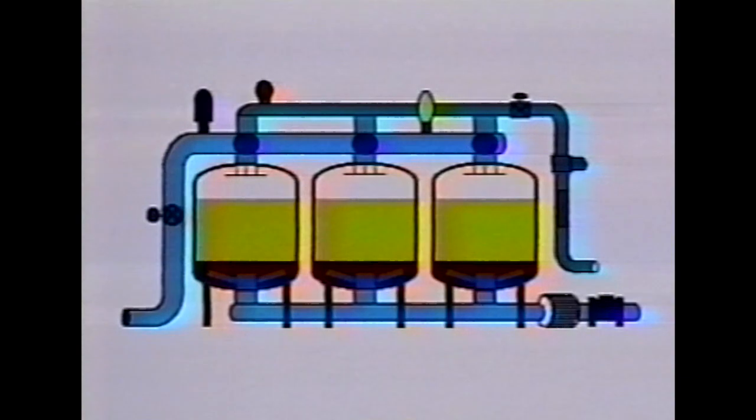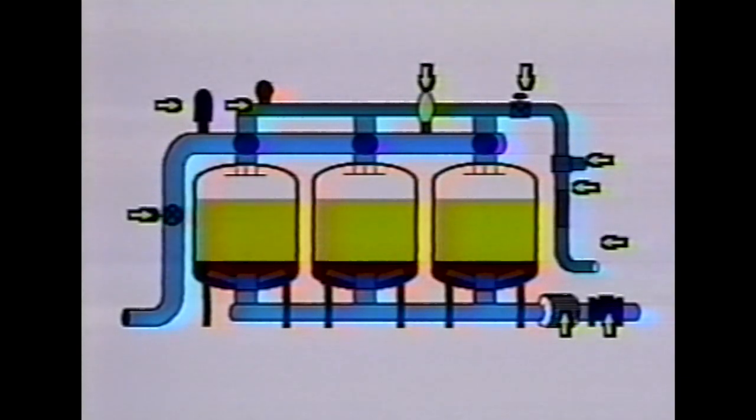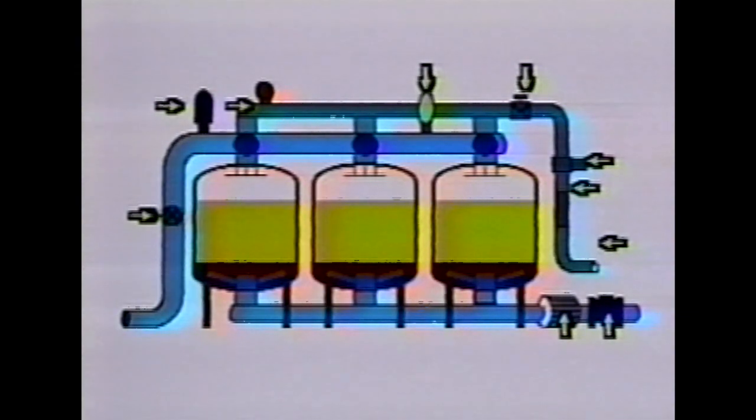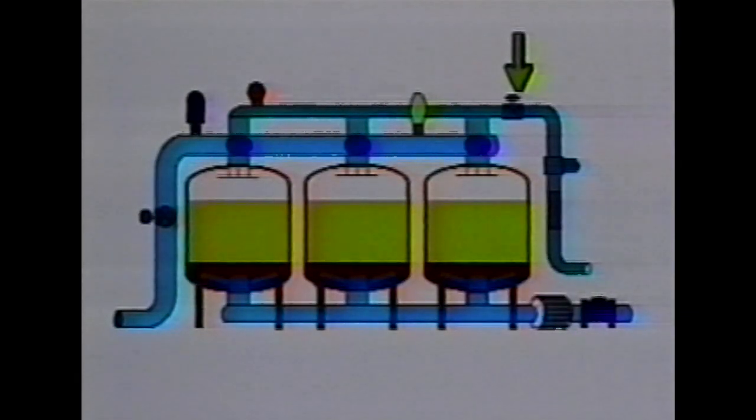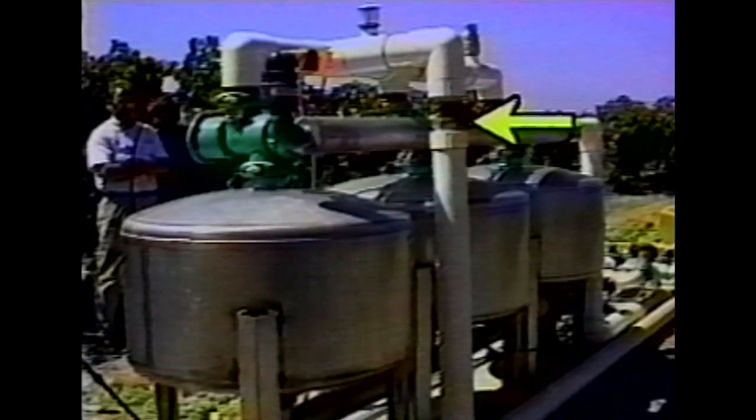This figure illustrates the proper types and locations of various accessories needed for media tanks. There are many essential accessories for the media tanks. These include the backflush flow rate adjustment valve or backflush flow rate restrictor. This valve can be a gate, butterfly, or globe valve located downstream of the backflow manifold after the last media tank.